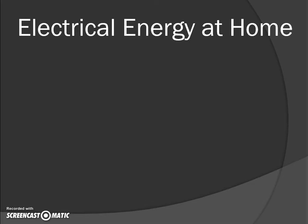If you look at page 647 in your textbook later on, starting from the power plant, you have about 11,000 volts coming out of there. And it gets stepped up so that it can move quickly through those power lines. And then once it moves through those power lines, it has to step down before it can be distributed to your home, to your neighbors' homes, hit a second transformer, and then come into your home.